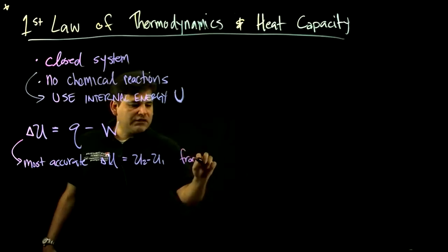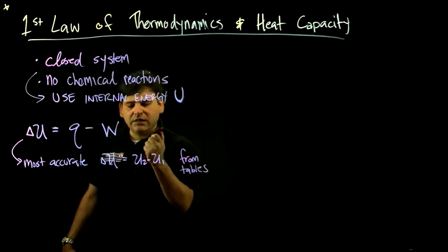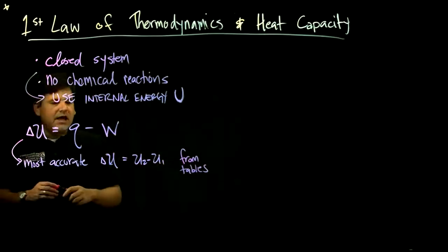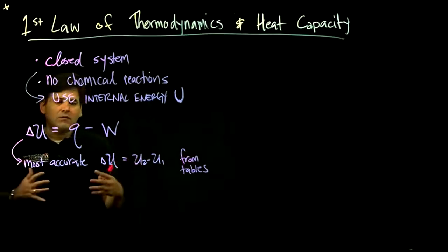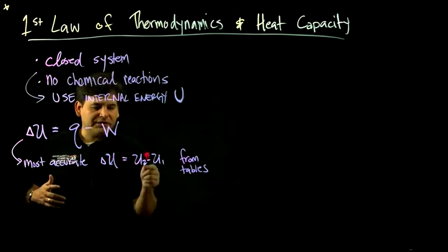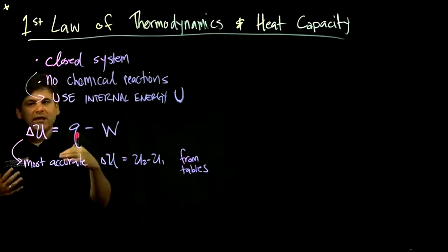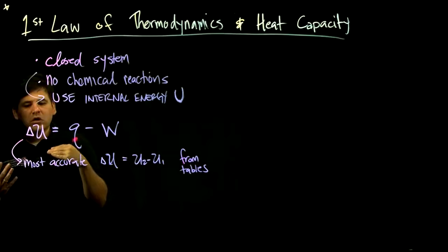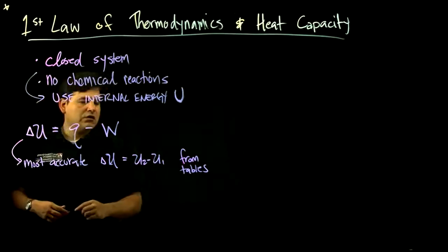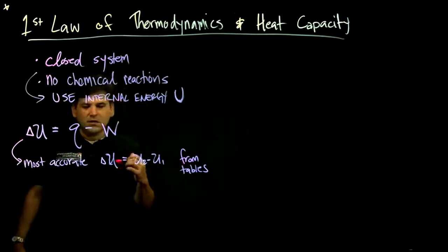Just find a good table for the specific material you're interested in, like water. When you're working with water, we commonly have liquid, vapor, or a mixture, and that's part of the process of determining these energy values. But when you're looking at a table, those are accounting for everything and just give you the value that would be useful in the first law.